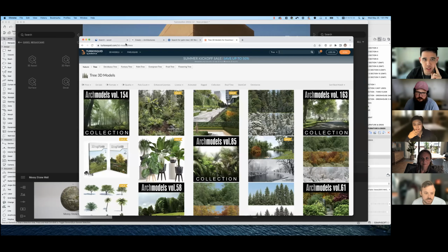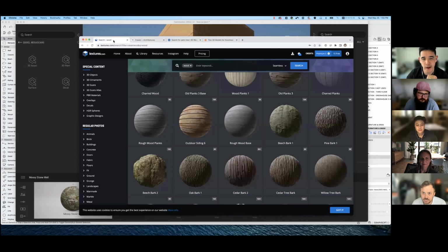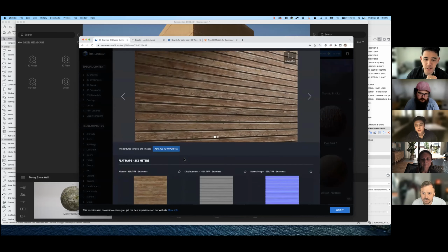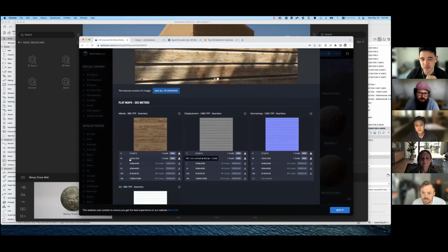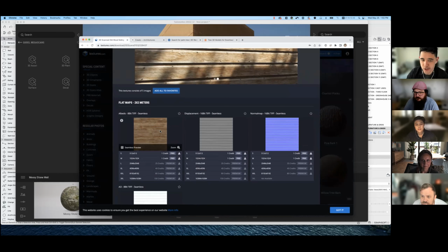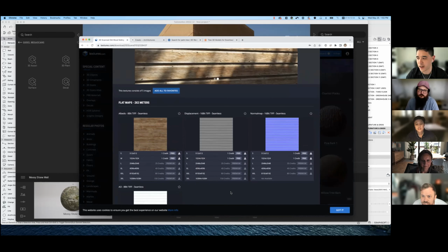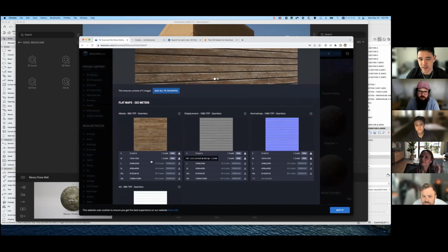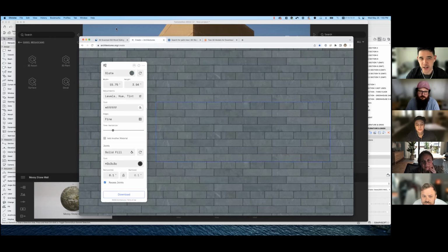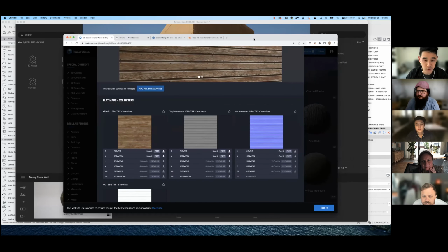Yeah, that's a good thing to keep in mind. Usually with the 2D textures, there's not too much to worry about. In this one, we're actually limited on a free account to the size you get, which is about 1,000 pixels. That's usually good enough for most of my purposes. If you're doing a path traced render and you need this special texture looking really good, that's when you ask the BIM team if we can buy you one of these higher versions of it, which we certainly do. Most of the time, any texture you can download here under 10,000 pixels is going to look fine, and it's not going to blow up your model.